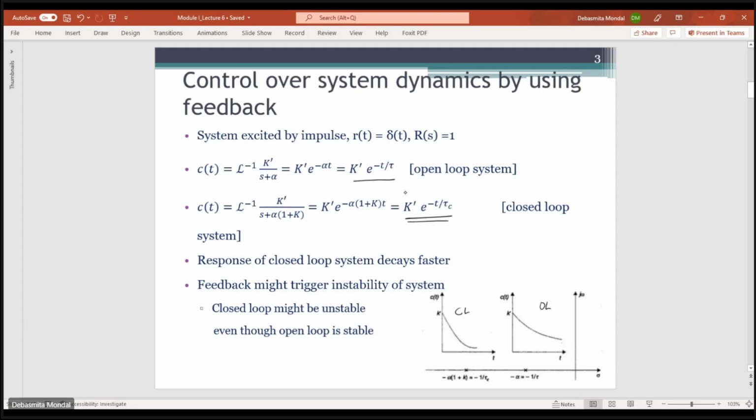Previously we saw that any variation in the feedback sensor gets directly reflected on the output. So we have to make sure that the feedback sensor we are using has very low parameter variations. And also, obviously, for better measurement, the signal to noise ratio should be very high.